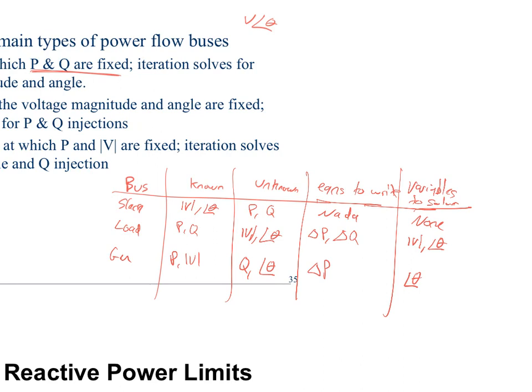All right? And those are the three bus types: slack bus, sometimes called a voltage bus, PQ, or PV. Don't get confused by the different names of buses, because if I have a generator here operating at 100 megawatts and maintaining a 0.9 lagging power factor, what type of bus is that generator connected to?